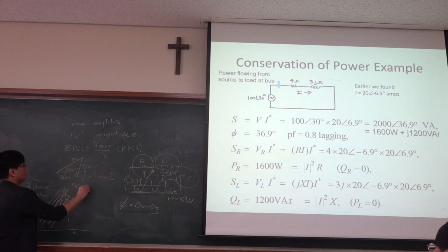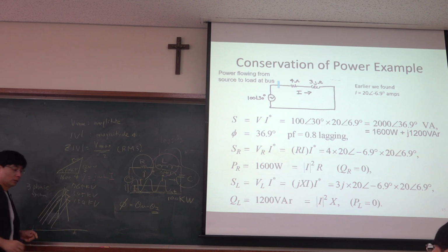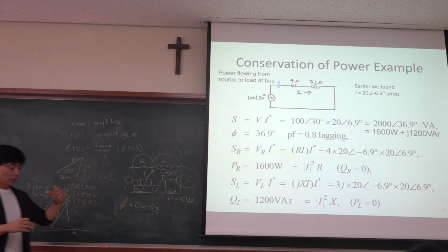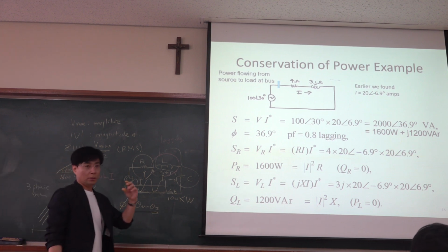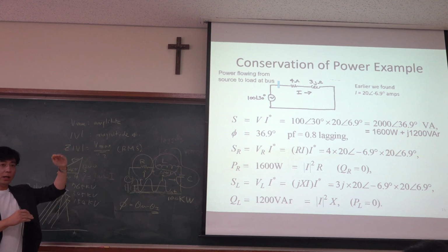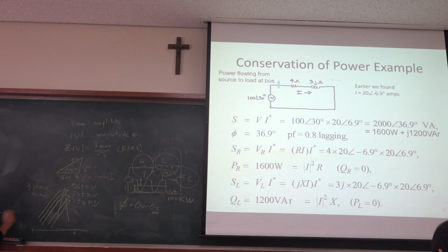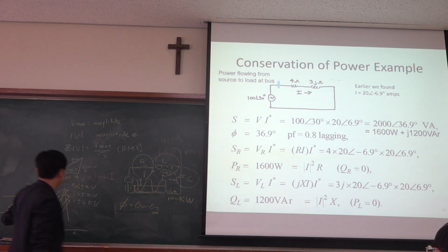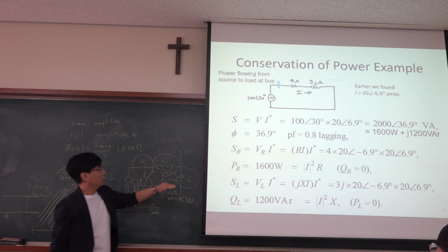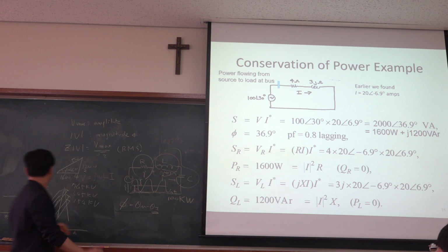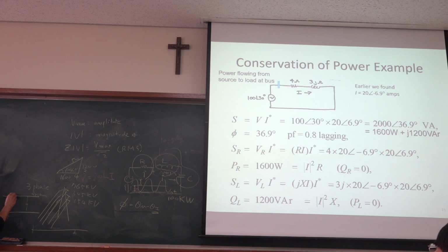Even though air is almost like an insulator, because this voltage is very high, between the ground and the high voltage line we have a small capacitance component. So this transmission line has the inductance component and the capacitance component, and also some very small resistance component.